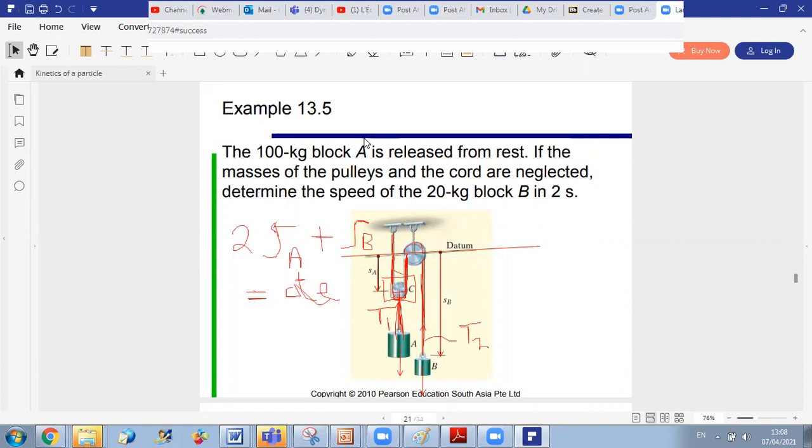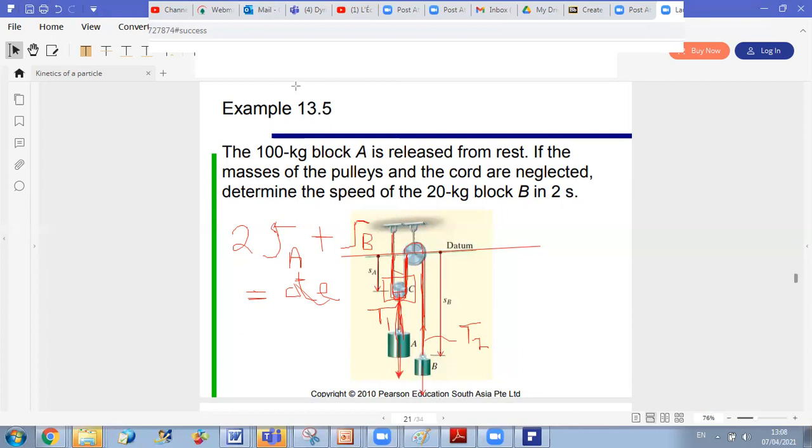For example, if you apply a force here that is variable, let's say you are putting a force F, function of time. If I tell you the applied force at A is F equals 2t, for example, then when you solve your system, you will have the acceleration and tension as functions of time. But because you have a constant force that is driving the motion, you will have constant acceleration at the end.